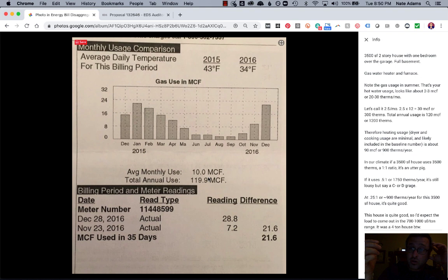It's 35 cents a therm, but the meter fee and then the other add-ons that they put on as part of the bill pump it up to somewhere between 70 and 80, depending. If they don't use very much, they're going to be on the high side. If they use a lot, it dilutes the meter fee and it's not as much. So you want to have an idea. And so 900 therms times, let's say 70 cents a therm, whatever, is $630. So their heating cost for the year is going to be between $600 and $700.